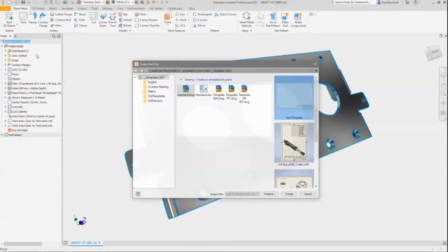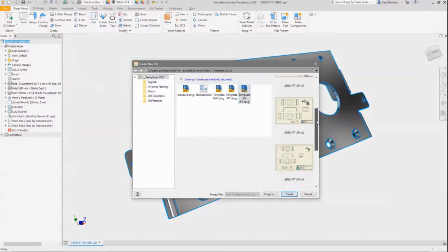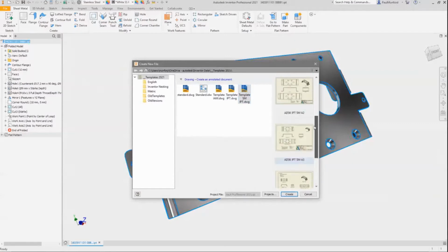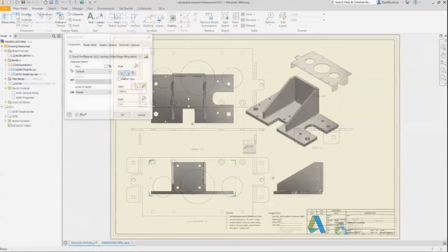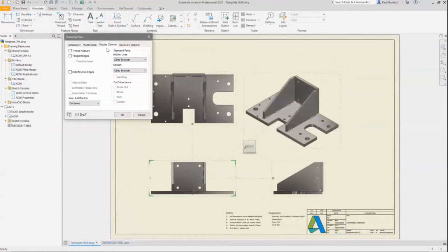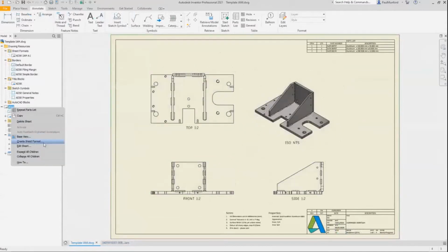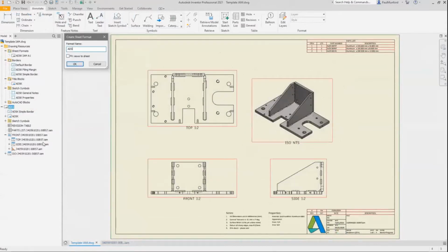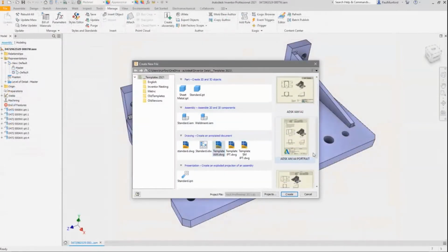Sheet formats in Autodesk Inventor are a great way to start a new drawing, with the drawing views of your design automatically generated from a pre-selected model. In Inventor 2021, we've made sheet formats easier to find by adding them into the dialog for drawing creation. View layouts saved as sheet formats now retain view settings such as edge display, and we've included a new fit to view option to automatically scale your views to fit on your sheet.